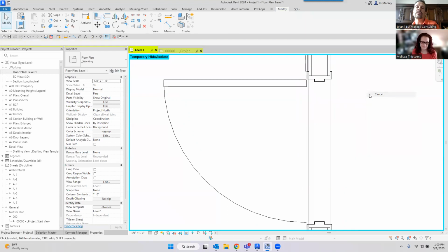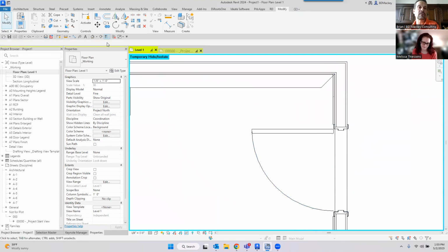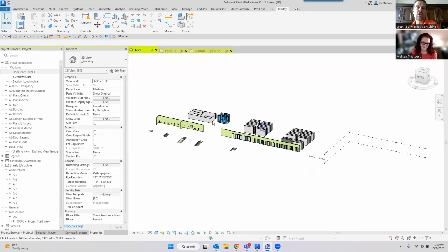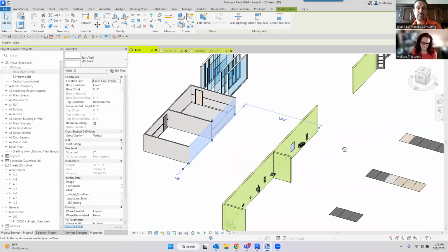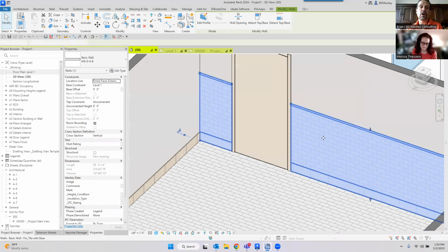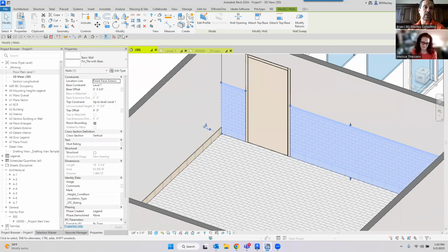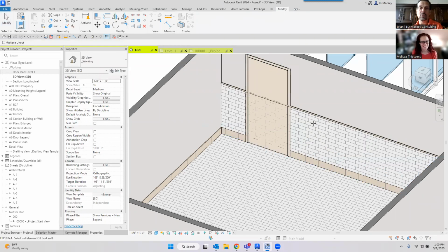Well, my next brilliant idea was, hey, in my door, I want to go ahead and add a couple voids. So if you have a finished material, you can just use the cuts geometry tool for that area. What I meant by that is right now you can see I've modeled this wall coming across, and this wall is great. It all looks cool, and it's being cut at the door. I'm going to go ahead and uncut this real quick. Oh my God, I'm so not used to the new icons in 24. Cut is over here. I'm going to say uncut. I'm going to go ahead and uncut this by the door.